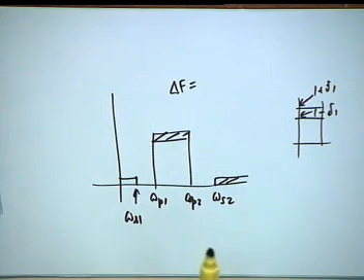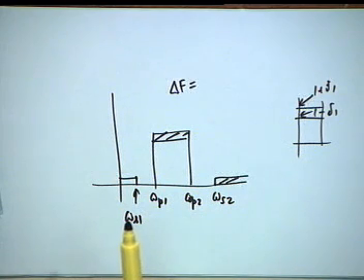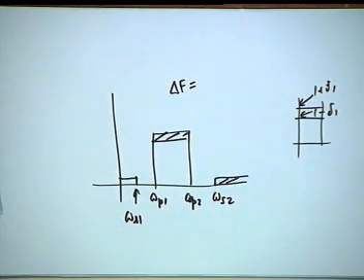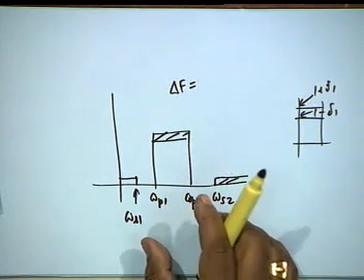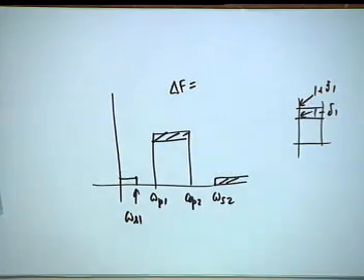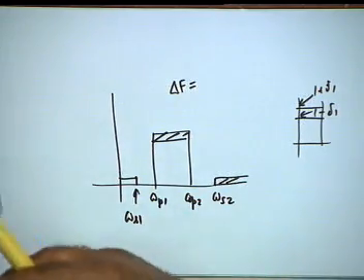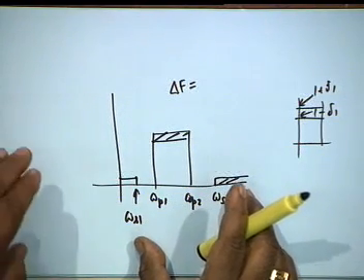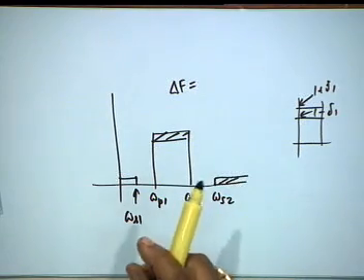Do not change omega p1 or omega p2. Agreed? Then only you can apply this formula. Even if you make a mistake here, the formula is only an estimate. Only thing is it will be widely divergent, whereas if you exercise this caution, life may be slightly easier to converge on what you ultimately want.